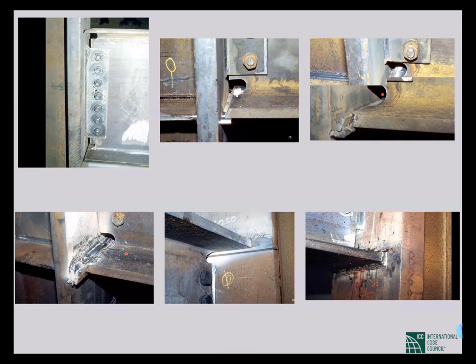And you can see there are some holes near the web level and near the flanges. These holes are called weld access holes. Because we have to weld the flanges, we need some holes so that the welding electrode sticks can enter.